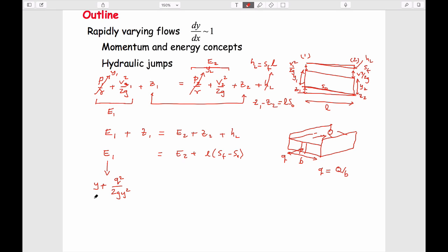This is the depth of flow. This would be 1 in this particular case, and this would be 1, and likewise for E2. And so this is just this term which includes these two components, the pressure head and the velocity head, the inertial term. But we've substituted a velocity which would change potentially as you go downstream because the depth might change, by a single term which will never change. So we know that we can get this magnitude here.